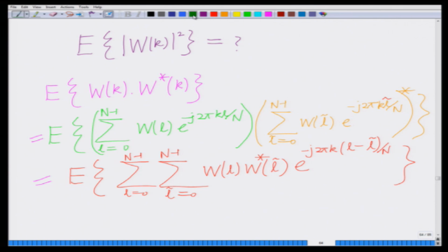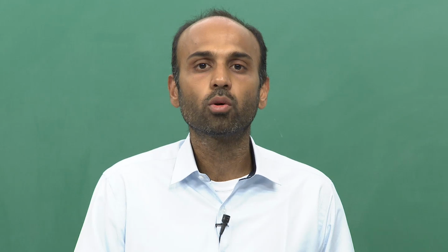And now if you look at this inner expectation, the expected value of w_l times w_l tilde conjugate, we already said that the noise samples w_l and w_l tilde are independent, therefore uncorrelated.